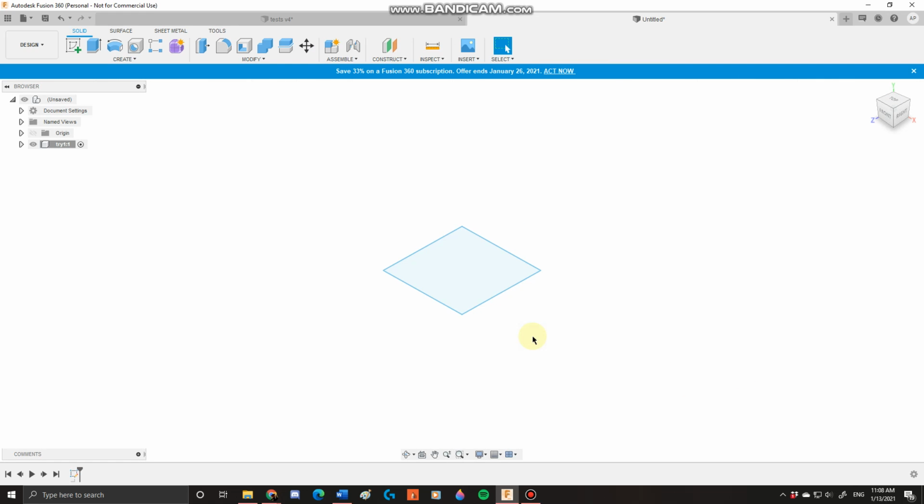With that, it puts us into our orthographic view, and we can see our sketch and move it around in 360 workspace by clicking Shift and the middle mouse button to rotate around a certain point, and just press the middle mouse button to pan along your workspace. That's the basics of moving around your workspace. So for now, we'll move on to creating our shape.